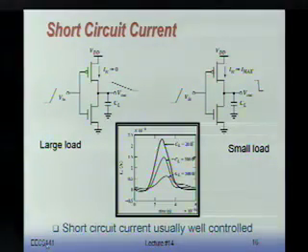You have dot measure commands that say measure the 50% point from this, 50% point here, bingo, you get the results. And it gives you the propagation delay in one shot. You don't even have to look at the waveforms. So dot measure allows you to do propagation delay outputs quite easily.